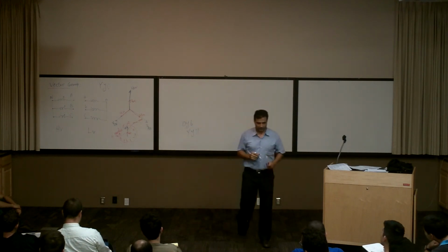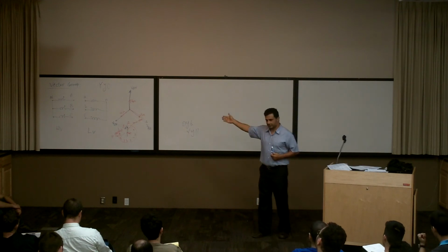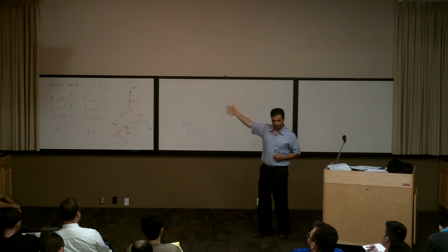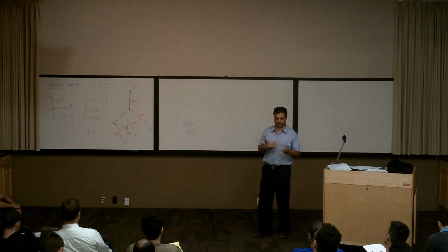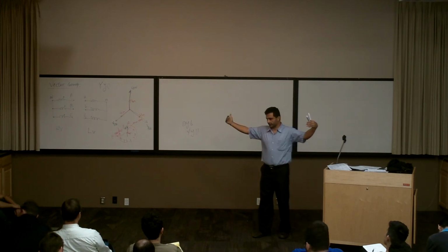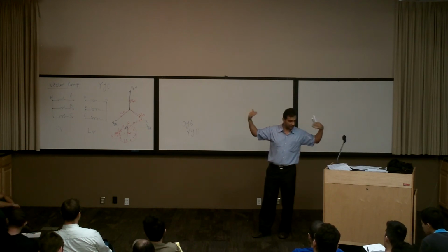0 is very easy. So the vector group of this transformer, which I put on the board, is capital Y, small y, 0. It means there is no phase shift between the phases. Whatever is a phase in the primary is a phase in the secondary, right? When the number is 0, it means they are exactly in the same phase.